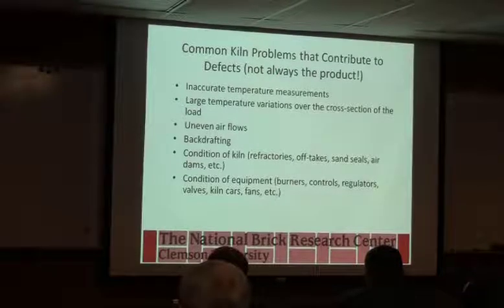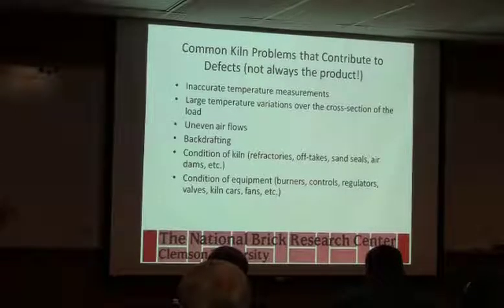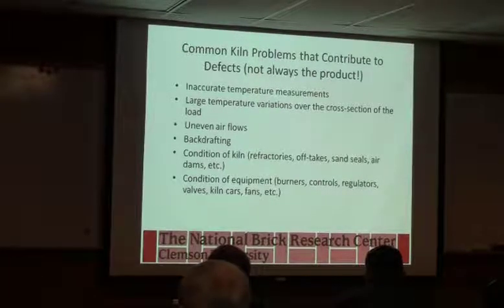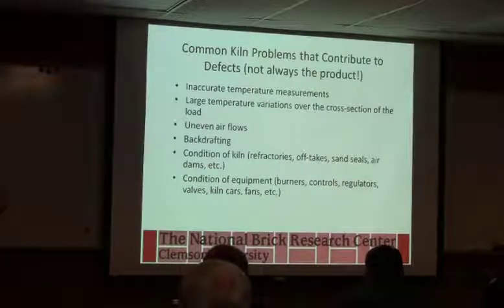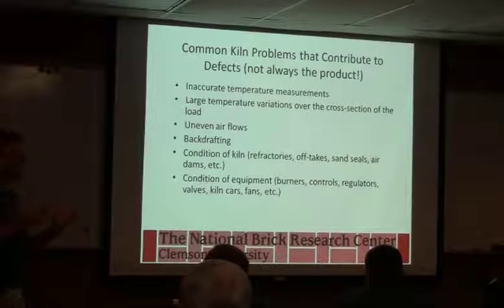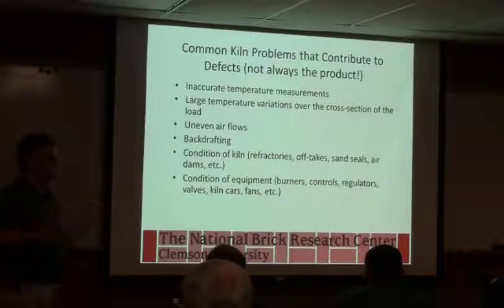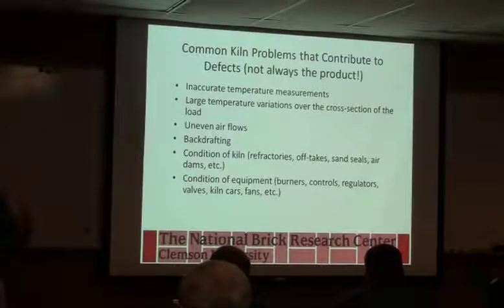I can get the flame temperature with 4 burners on this periodic kiln that's probably 10 by 6 feet. With 4 burners on, I can hold temperature at 200 degrees inside the kiln, because there's just so much air going in that is basically taking the BTU and absorbing it, keeping the temperature from rising. So you're basically cooling the flame.